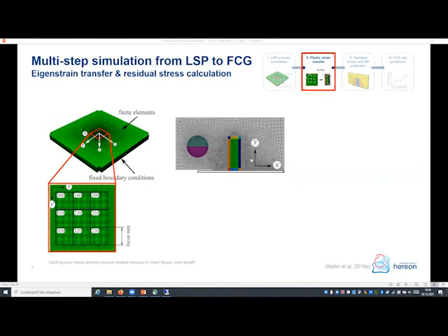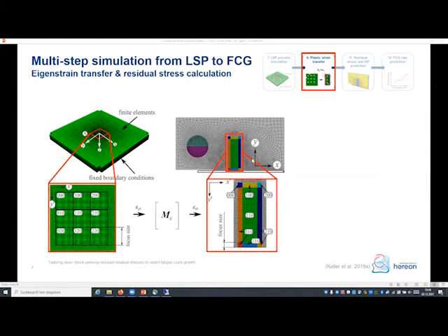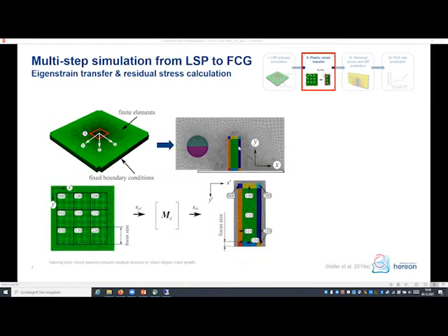I take the centered area, for example, here labeled with 110, and apply this to the larger centered area of the larger peening patch, here labeled with 110 as well. And of course, the edges stay the edges, and the corners will stay in the corners. So I can build a large peening patch here for the CT specimen where I model just the half of it.